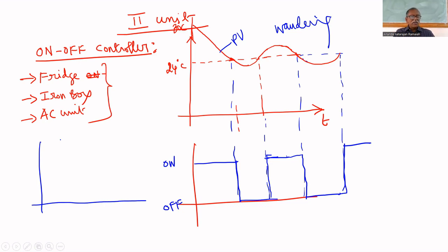They will put some set point, say 220 volt set point. Suppose incoming voltage is less than 220 volt, it will add more. An auto transformer will adjust the number of windings so that voltage will be maintained at 220.